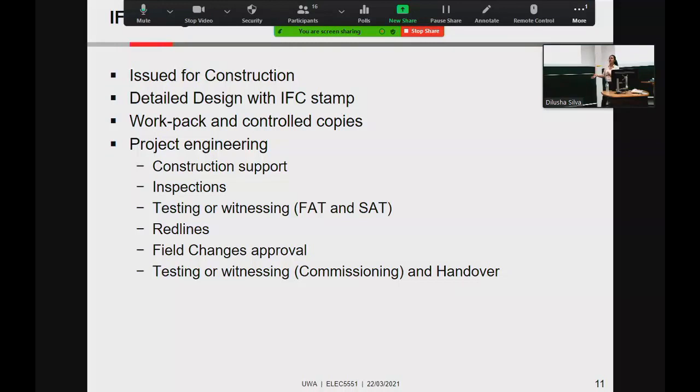So the rack is built, tested, and ships to site. On the site it's fitted out. You get some phone calls, you answer questions, cables are done. You go there to witness a SAT, site acceptance test. Similar to FAT, it's equipment based. Say for a radio base station, you will test the transceivers, maximum power, their receive sensitivity, etc.